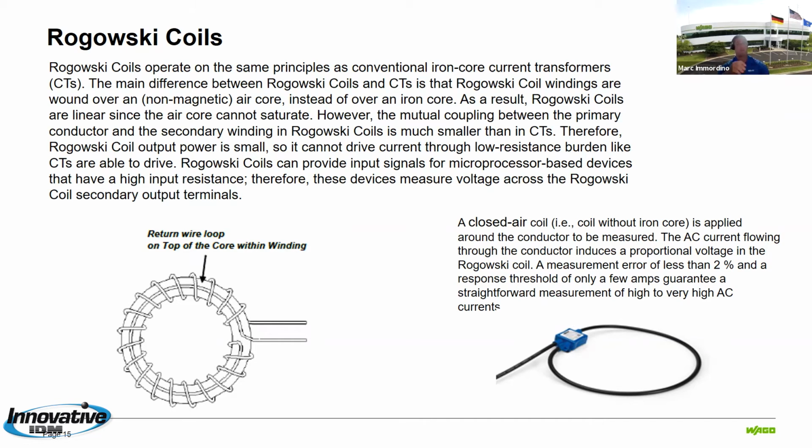You're talking about large conductors, high voltage, high current capacity. With the Rogowski coils, it plugs right into this base module here. So you can unplug it, wrap it around the main conductor, plug it back in, and you're off and running. Something like a split core, but much easier to handle. The base unit in blue there usually would fit in the palm of your hand. So they're really small.